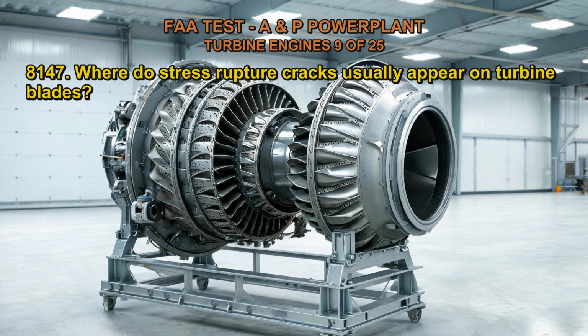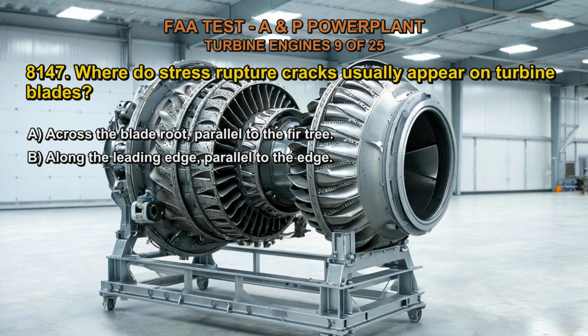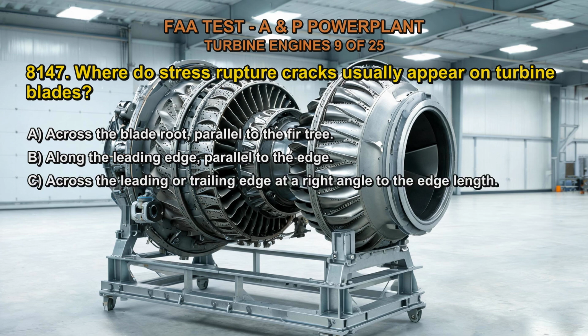8147. Where do stress rupture cracks usually appear on turbine blades? A. Across the blade root, parallel to the fir tree. B. Along the leading edge, parallel to the edge. C. Across the leading or trailing edge at a right angle to the edge length. The correct answer is C.